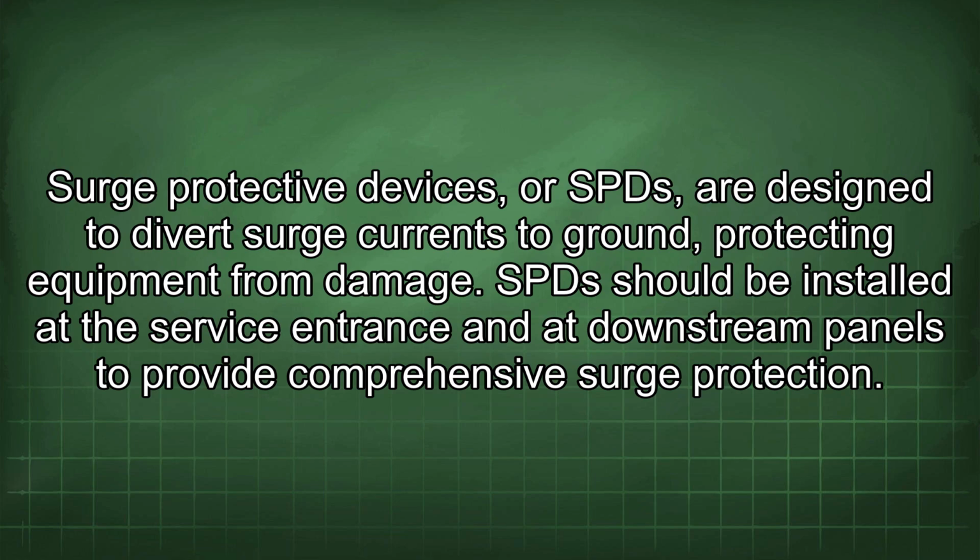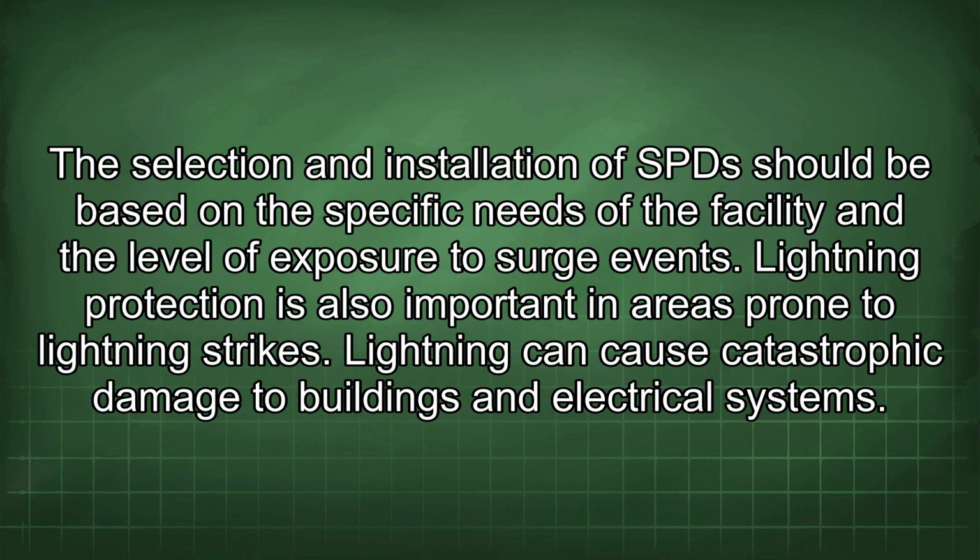SPDs should be installed at the service entrance and at downstream panels to provide comprehensive surge protection. The selection and installation of SPDs should be based on the specific needs of the facility and the level of exposure to surge events. Lightning protection is also important in areas prone to lightning strikes.